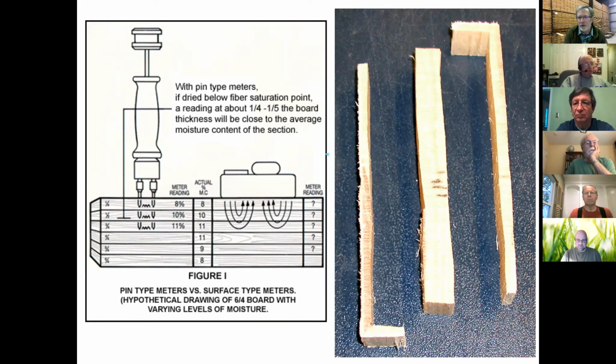These are just ways for you to find out what the moisture content of your wood is and what the distribution is before you get started, because knowing that distribution sometimes is more important than the average, particularly if you're not certain about the person or the operation drying your lumber, or if you've held that lumber in storage for a period of time.